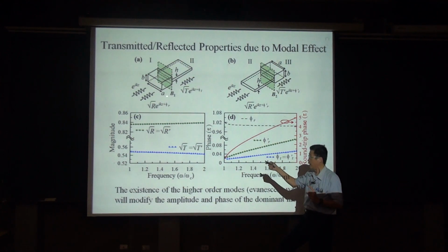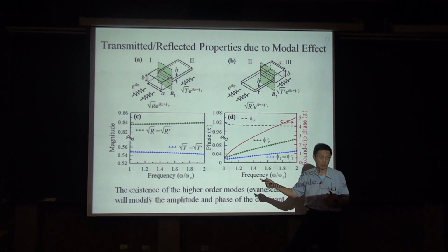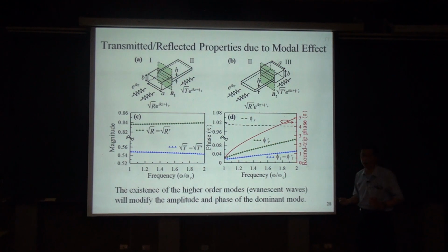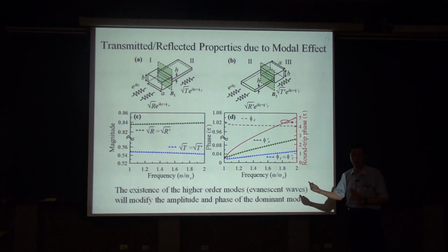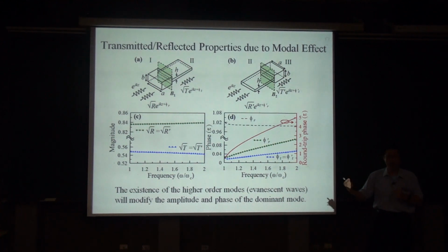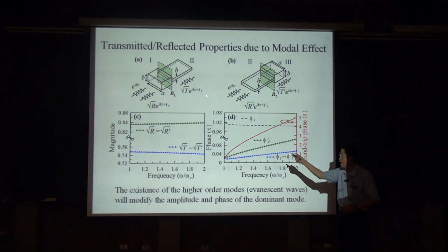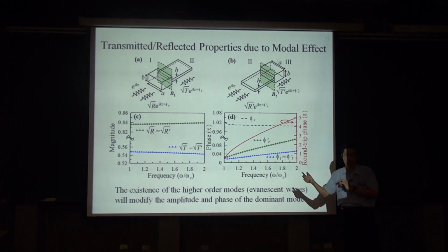of transmission and reflection. By doing so, we can simplify the problem into quasi one-dimensional. We just reduce the three-dimensional problem into one-dimensional. And the other high-order modes come to here. We have extra phase, and transmission and reflection will be slightly changed.